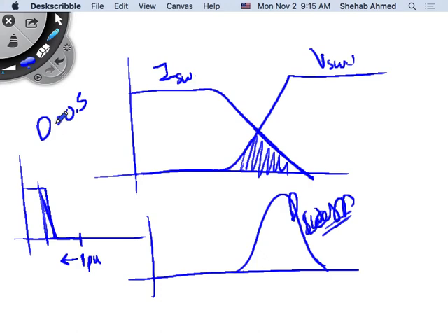It's like needing 1 second to get out of this room; it's a finite amount of time. The current in the switch needs time to go up and go down, and you need it to go up and stay up for a certain period of time, which is your duty ratio. If the period keeps shrinking, you can no longer go up, go down, and stay up for 50% of that period. So there's a limit on switching frequency dictated by your rise and fall times.